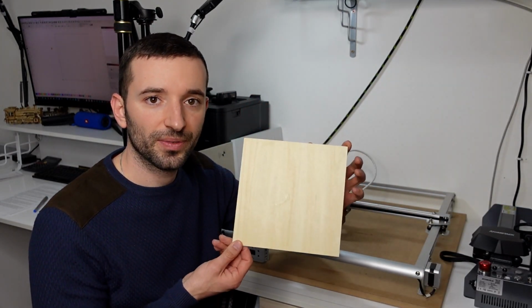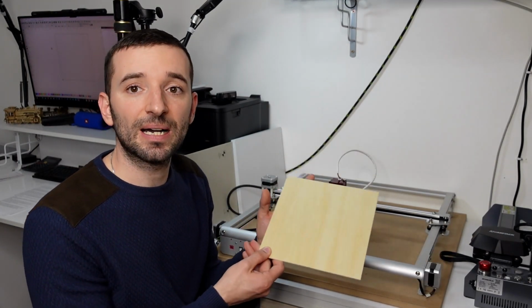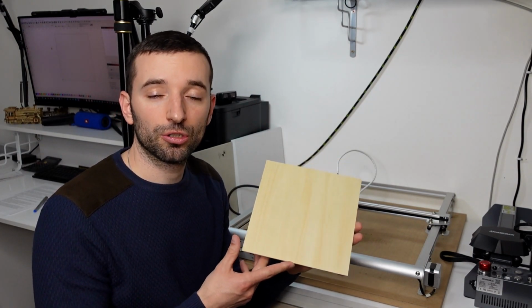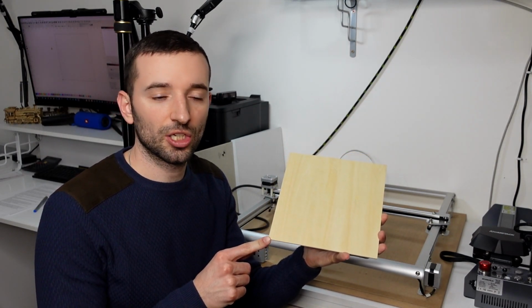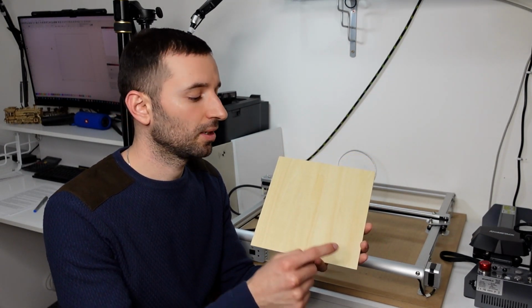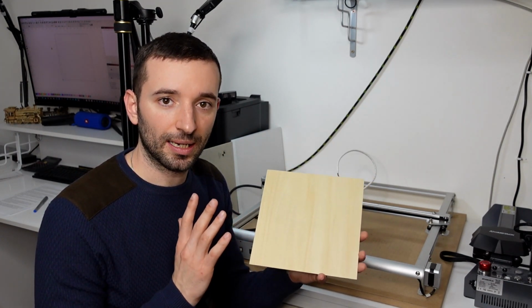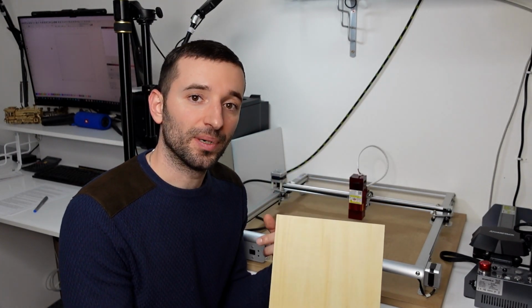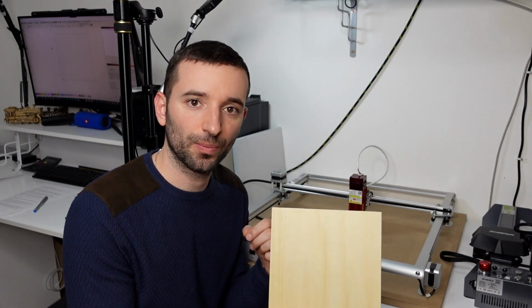Okay. Similarly, we will also have the workpiece origin and coordinate system. And so if we take, for example, a sheet of plywood, now this plywood is smaller than the area, so it will be placed somewhere in the machine. And so the workpiece will also have its own origin. Okay, we can choose it to be this corner, we can choose this corner, the center of it. We can do whatever we want. This is something that we can approach within the controlling software. Now, let's jump into LightBurn so that I can show you how you can change those settings from there.